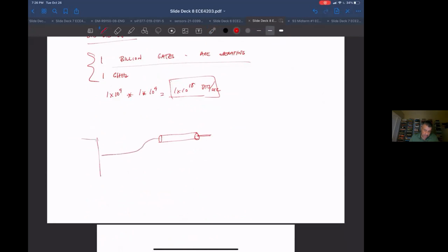So this goes to your microscope, not microscope, sorry, oscilloscope. So it's your oscilloscope probe. Your ground, just clip it onto the tip. Okay, so this makes a pretty good antenna right there. So I just hover it around your board and see how much electromagnetic interference there is, so what kind of signal this picks up that's just being sent into the world by the board itself.